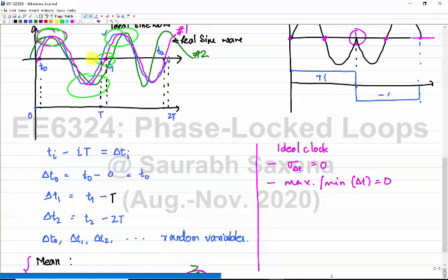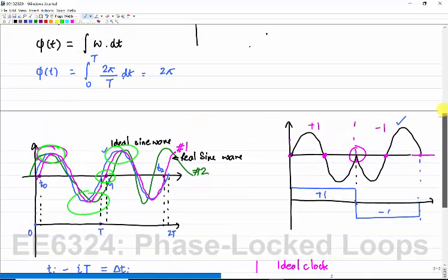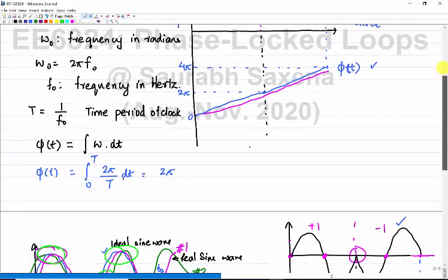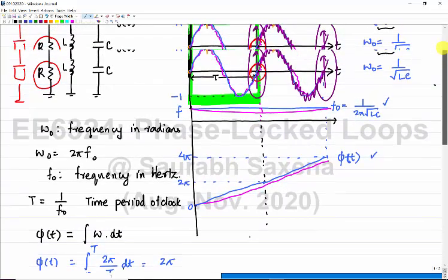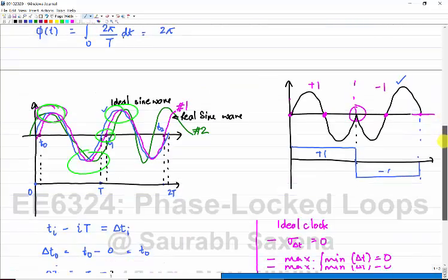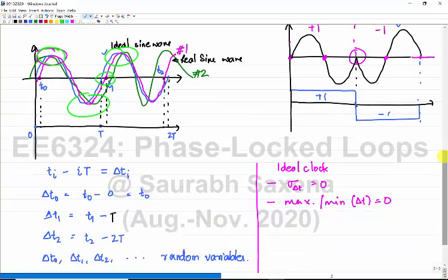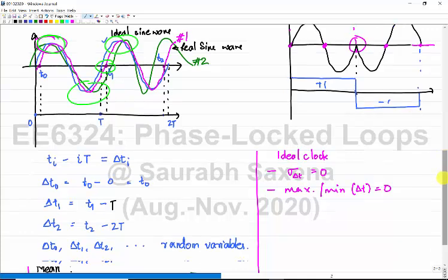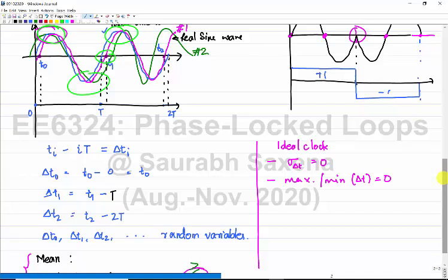The information we would like to have is a perfect zero crossing without any deviation. Amplitude can vary, it may be fine. In all your other courses you were more worried about the voltage, but here you are not worried about the voltage, amplitude and other things as such. You are more worried about zero crossing because that marks an event.